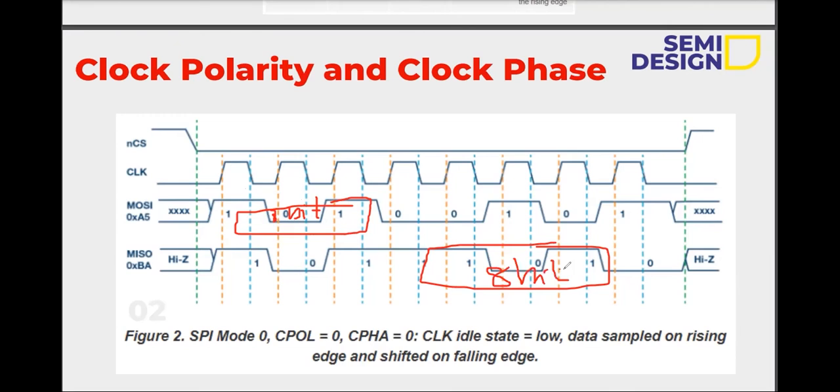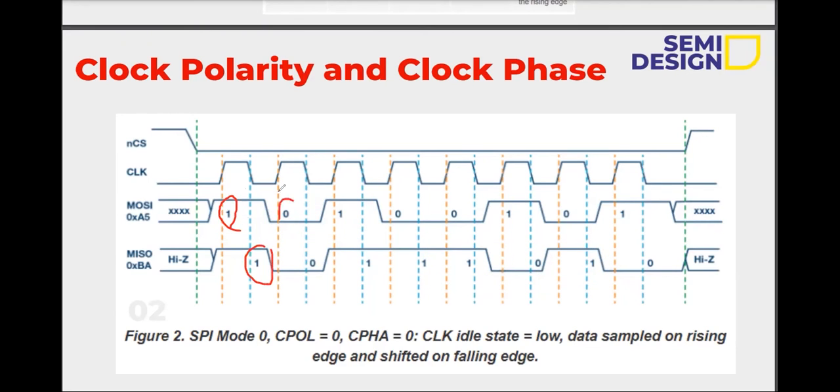the 8 bits totally. But here, in SPI, it is not like that. It is sending one bit, receiving one bit, sending one bit, receiving one bit. That means everything happens in a full duplex manner.